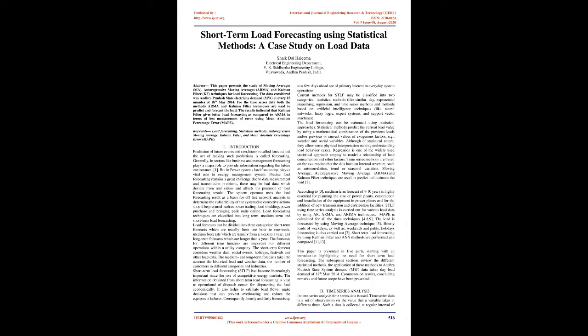The system operator uses the load forecasting result as a basis for offline network analysis to determine the vulnerability of the system, else corrective actions should be prepared, such as power trading, load shedding, power purchase, and bringing peak units online. Load forecasting techniques are classified into long-term, medium-term, and short-term load forecasting. Load forecasts can be divided into three categories: short-term forecasts, which are usually from 1 hour to 1 week, medium forecasts, which are usually from a week to a year, and long-term forecasts, which are longer than a year.